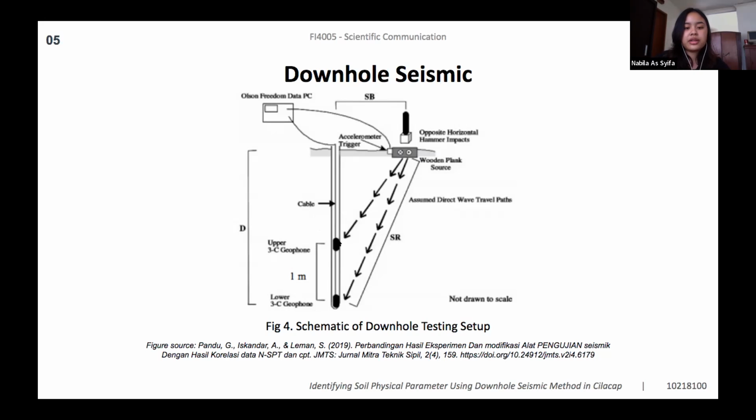So the receiver is in the form of each geophone, and the wave source is from the shot or blasting points here. This method uses direct wave propagation, where the geophones receive and detect the first wave that reaches the geophone without seeing other wave refraction.